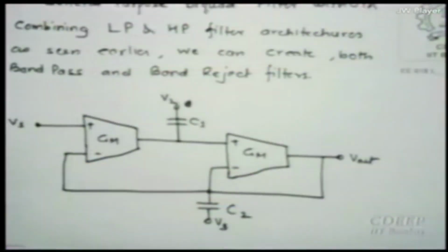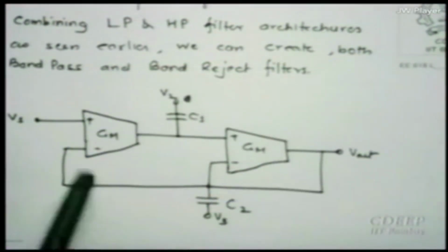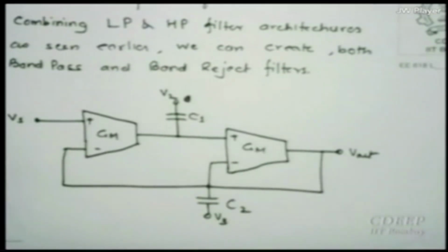Okay, so here is the circuit, which is the quad one, biquad. There are two OTAs available. Right now I assume that their GMs are the same. On a silicon chip this is not a very wrong assumption. As close as I can make, their properties can be almost identical.